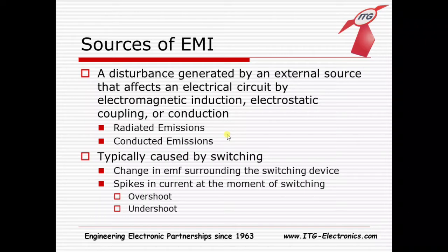The second being conducted, which is obviously the supplement to that. Anything that connects the source of the noise and the target or victim of the noise. Anything that is a conductive path that conducts that noise or emission or interference would be referred to as conducted emissions. And the source of EMI is typically through switching in some external source or a foreign signal that's being created.